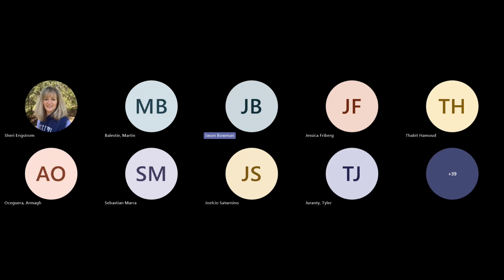So let's see. All right, Martin, have you tried or experimented with centrifuges or probably hydrocyclones? No big deal. Just wondering as regards applicable to known thickening devices. I think the short answer is no. I mean, with the DAF process, most digesters, when you get into these situations, you really don't want to go more than 8% or 10% solids. So centrifuges are probably a bit overkill from that perspective.